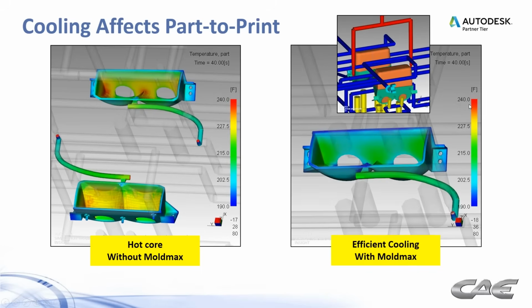And you can see we're on the same scale here, and we're able to get the red out, so to speak, with efficient cooling from the MoldMax. We also introduced a couple of baffles into there. So by doing so, we were able to reduce that temperature some, 25, 30 degrees in that area.